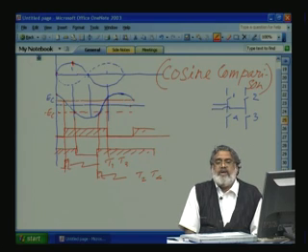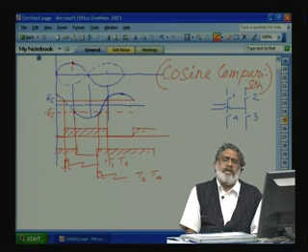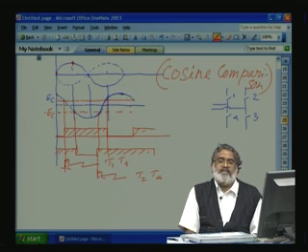Then we have talked about the 4-quadrant chopper. The 4-quadrant chopper is a single phase inverter circuit where we can have 4-quadrant operation, and with a proper PWM controller, we can have a unity power factor. So, various converter controls we have studied.